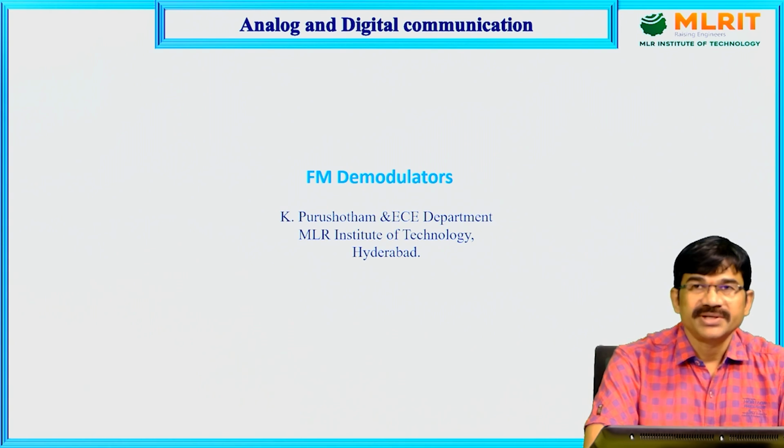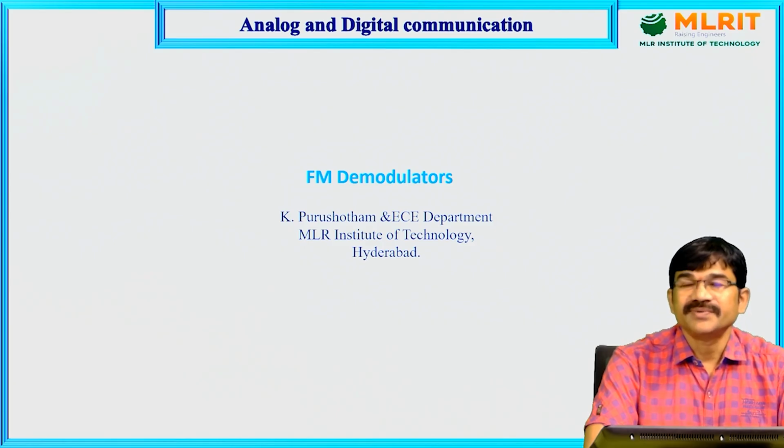In the previous class I discussed the different types of FM modulators we are using. Those are the two types of FM modulator, classified based on the value of beta: beta less than 1 and beta greater than 1. Beta less than 1 means narrowband FM, and beta greater than 1 means wideband FM. Narrowband FM we have generated, which is similar to AM, and wideband FM also we have generated.